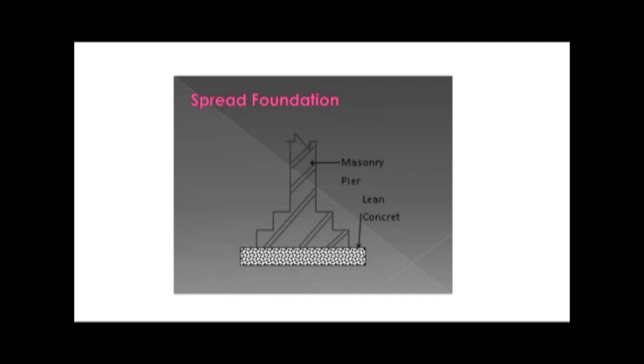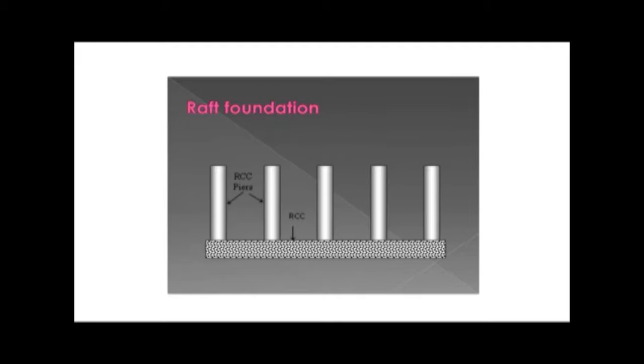Followed by, now we have pile foundation. When dealing with long span bridges and heavy loading bridges, a set of piles is installed and these piles are covered with a pile cap, providing the seat for the pier. We have a video in all these slides. If it will support, you can look here. If not, then you can easily go to YouTube and check for the mounting of the piles and the pile cap.